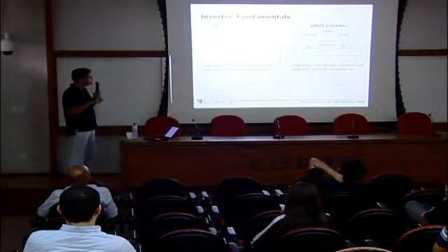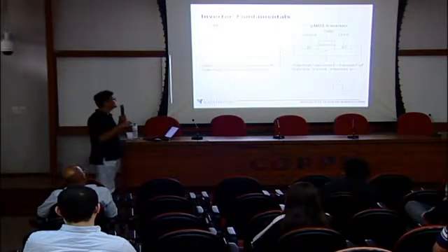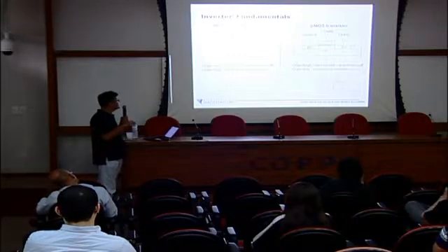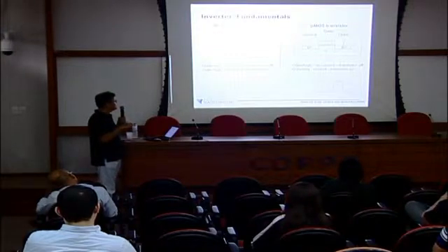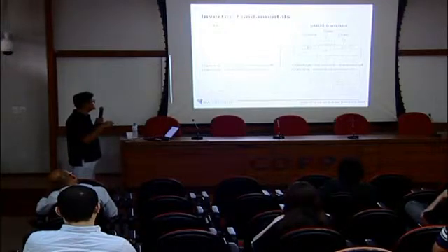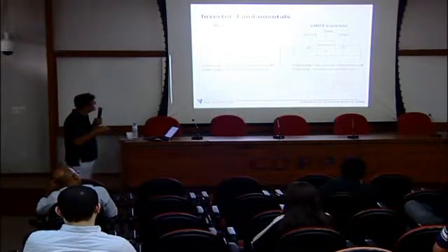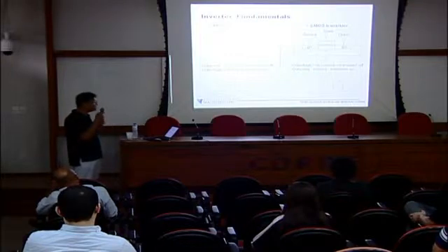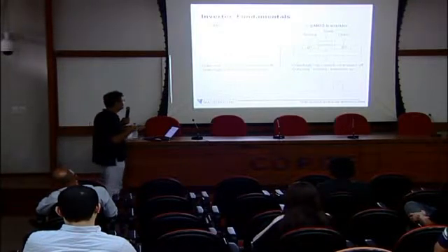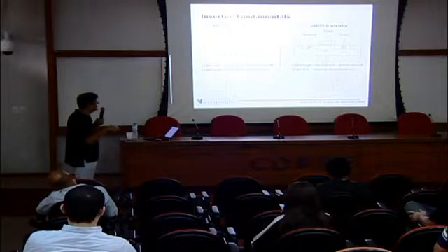That's why we call this semiconductor an NMOS transistor. And then this one is opposite. So if you see the structure, then we will apply a 0 in there. Then 0 means it's a negative. Then you will bring in the positive out there, right? Then P will form. Then no depletion zone. Then current flows, right? Then through the P we can make the current. That means it's a PMOS transistor. And if it's a 1, then you will attract more electrons to there. Then it will terminate the current. Then there is no current. So this NMOS transistor is symbolized with this, and then the PMOS transistor is symbolized with that one.